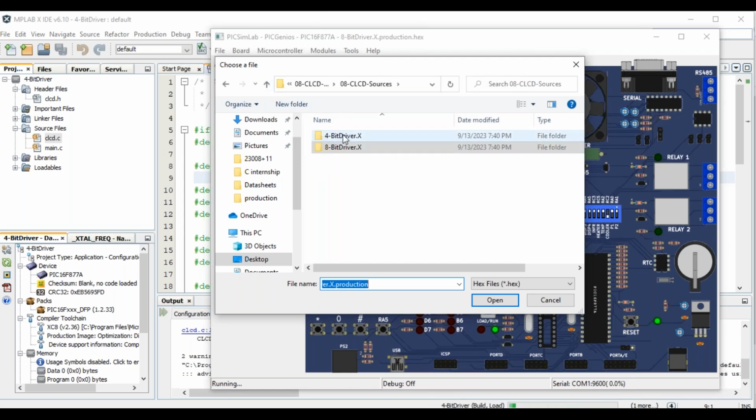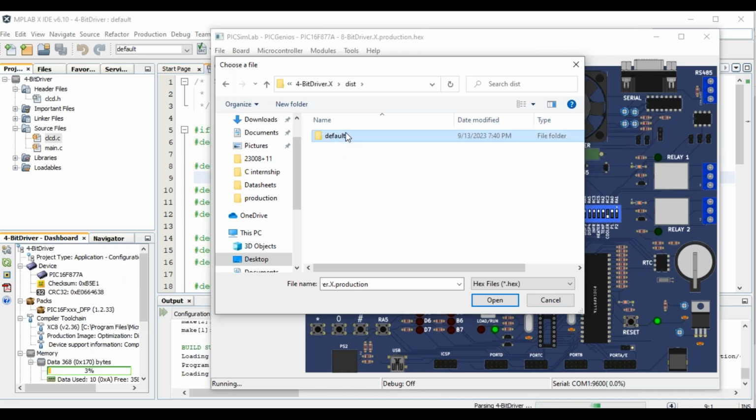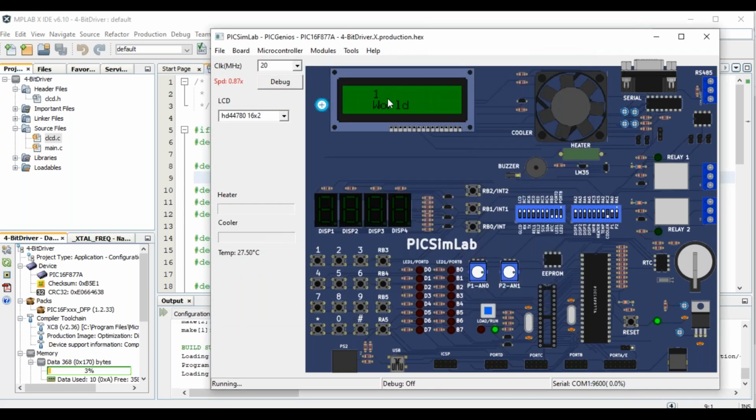you can just look at the CLCD write function. If the CLCD write function has the data written in one shot to port D, then it is configured in 8-bit mode. If the data is written 2 times, upper nibble first, then lower nibble, then CLCD is configured in 4-bit mode. So you can see Hello being displayed on line 1, 4th position, and World being displayed on line 2, 4th position. Clear?